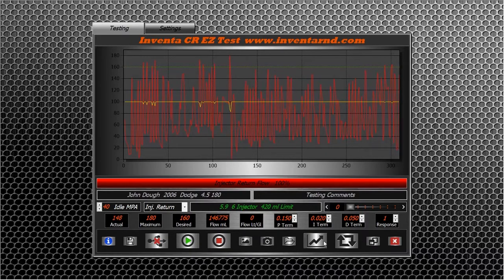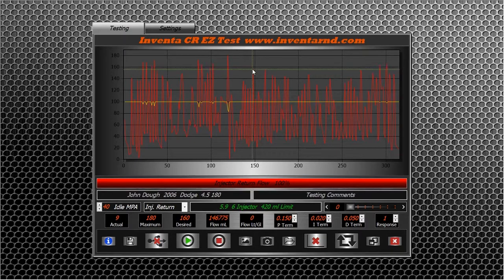And if you want to stop and say, all right, I want to know what was going on right there. How long did it take to get there, and what was the actual pressure? I see it's between 140 and 160, but now you can do it. You can say, all right, 14.7 seconds. The MPa was at 156.34, and you can keep clicking, and it'll add a new one at whatever point. If you want to get rid of this, you click off.